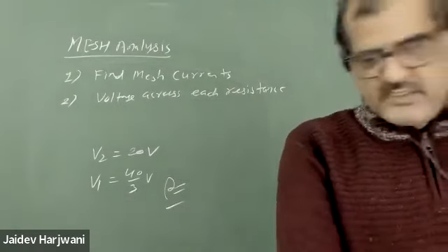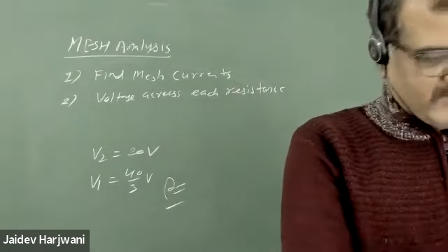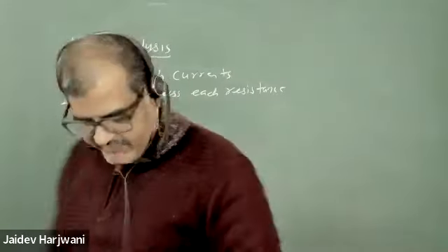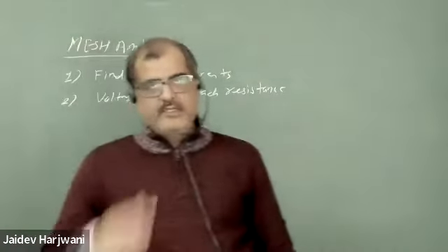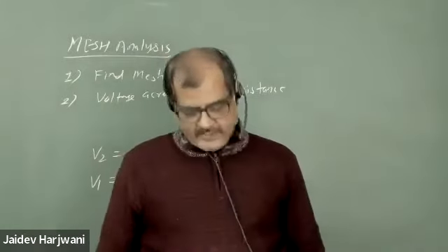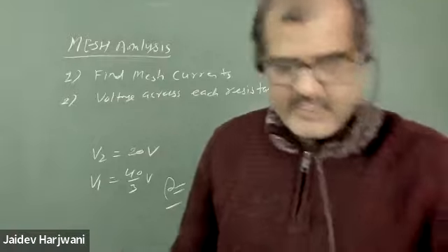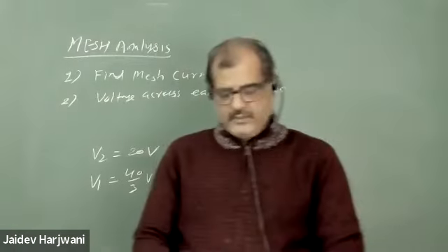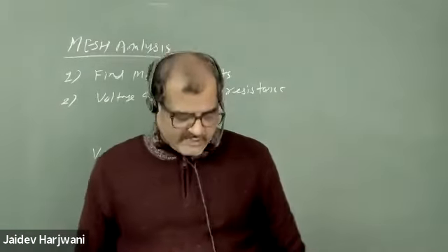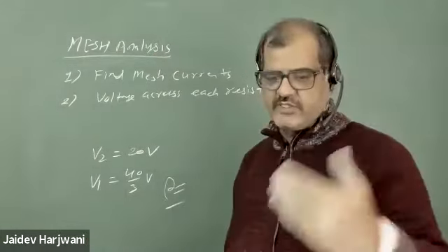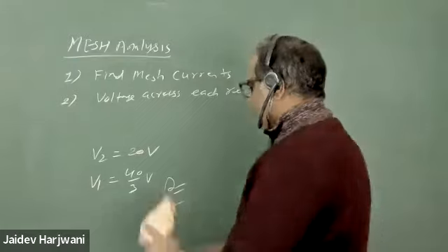Like nodal analysis, where we calculate nodal voltages, in mesh analysis we first identify the mesh and assign a direction to it. Assume a current flowing in the mesh and solve the simultaneous equations. Whatever equation we get for each mesh, we need to solve.